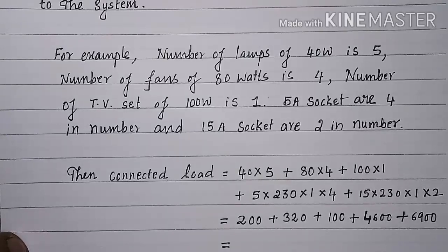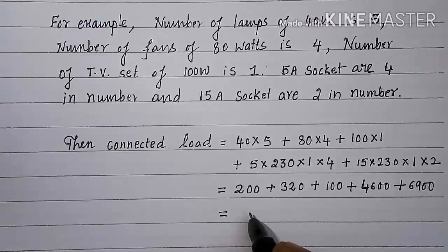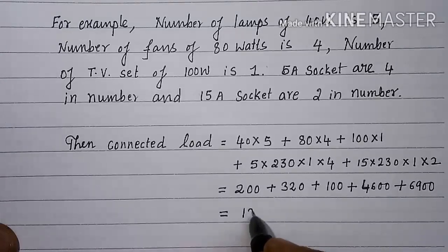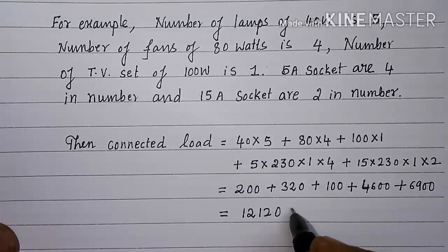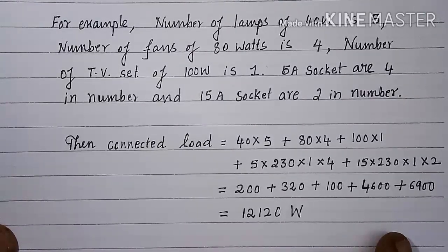Adding all these, we get 12,120 watts. So this becomes the connected load for the residence considered or for the premises considered.